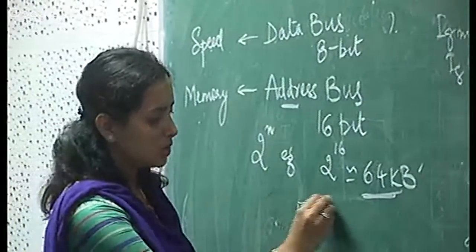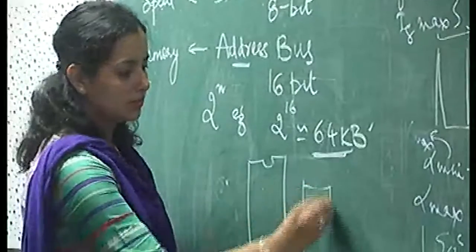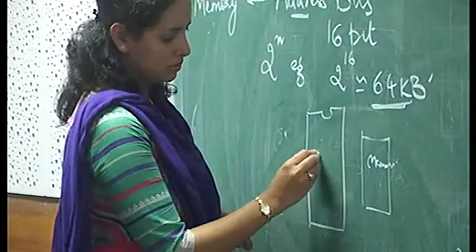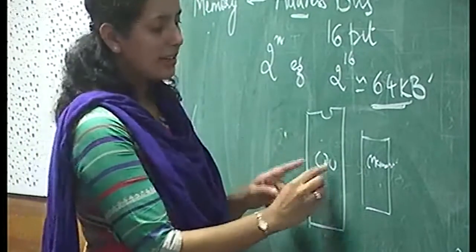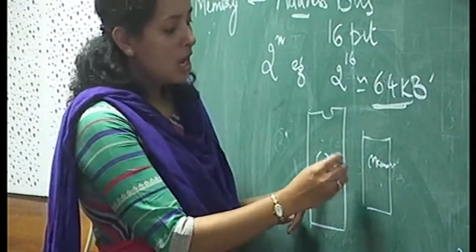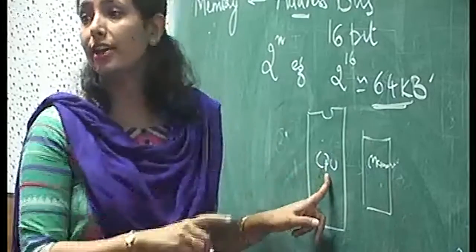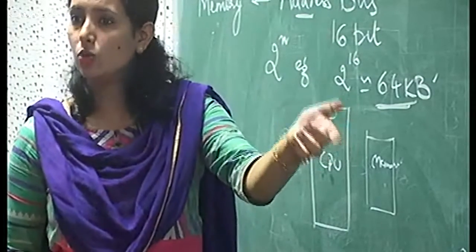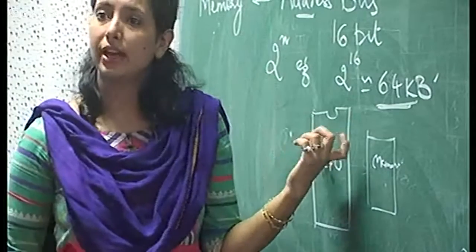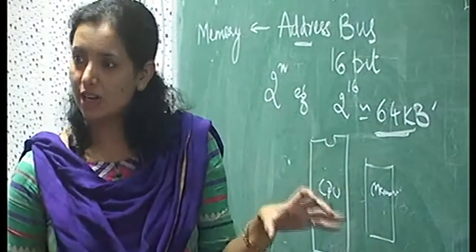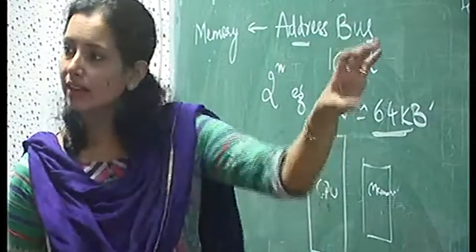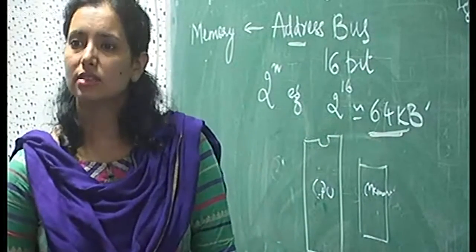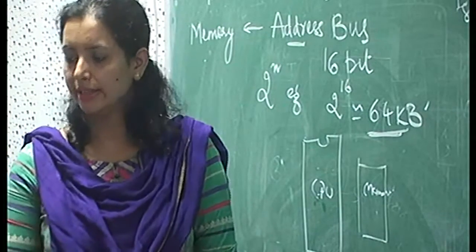Similarly, your memory contains some instructions. When the central processing unit inside the microprocessor has to fetch data which is stored in the memory, firstly it will send the address through the address bus. So when you ask me what is my address, I will tell you. Through that address, you will go to my house and bring me that data. Similarly, the microcontroller or a microprocessor, through the address bus, firstly sends the address. So the address line carries that address, and from that address the particular data or instruction is fetched via the data bus. So this is the significance of the address bus. Okay, clear?